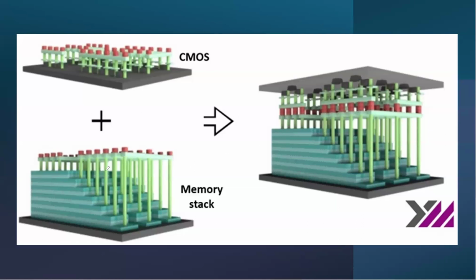In a NAND world, everything is patterned very nicely, and you could build many redundancy in these circuits, and therefore that's what all the memory is about. So the particle impact to yield is much less because they have built-in redundancy. So if you fail a little bit in a hybrid bonding interconnect, it's okay. It's not too bad. They'll fix it with their circuits. Okay. And that's the difference.